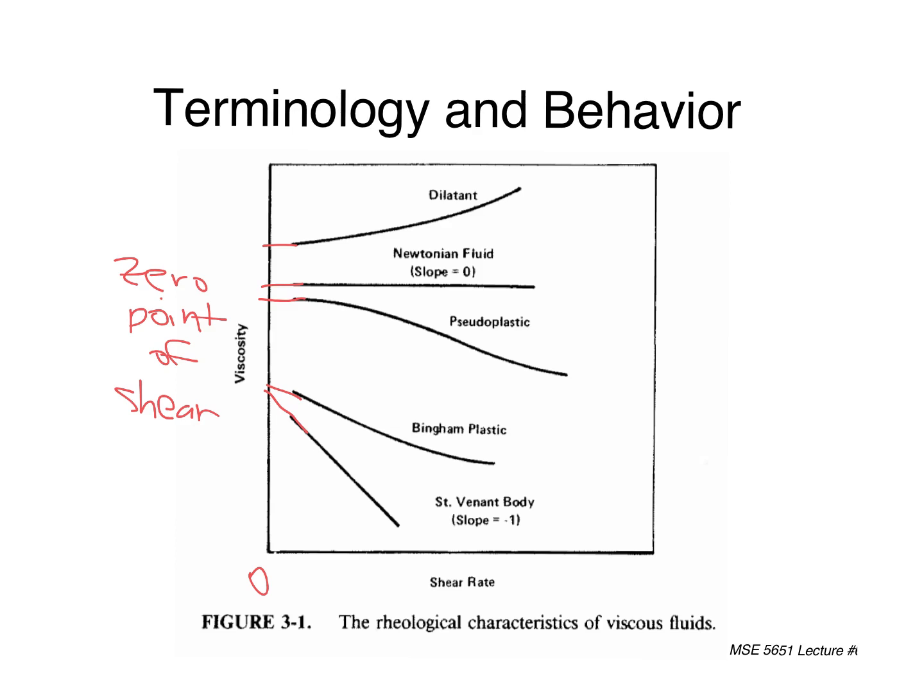And if we look at the behavior of these batches versus shear rate, all right, remember I said shear is really important, and this is an example because they're plotting this behavior to see how hard they have to work to shear this stuff. And what we're all familiar with is Newtonian fluids, because water is the one that surrounds us every day, and water is wonderful in that no matter how quickly you shear it, it always has the same viscosity.